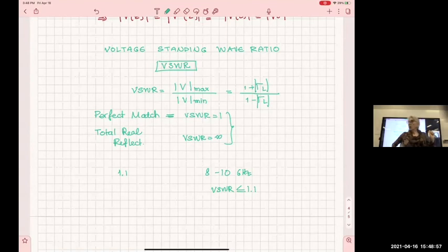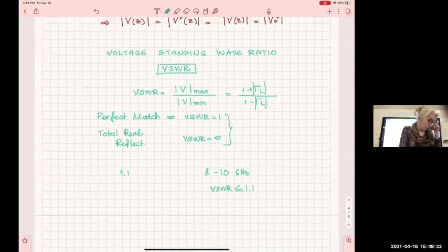All right? But they don't give you the reflection coefficient, they give you VSWR. And you know you have to be very, very close to 1. 2 is hugely bad, as you can see. 1.1, 1.05. If I start going to 1.3, then I'm getting a little concerned. These are the values you're going to have in mind. But this is how you're now going to solve this problem.